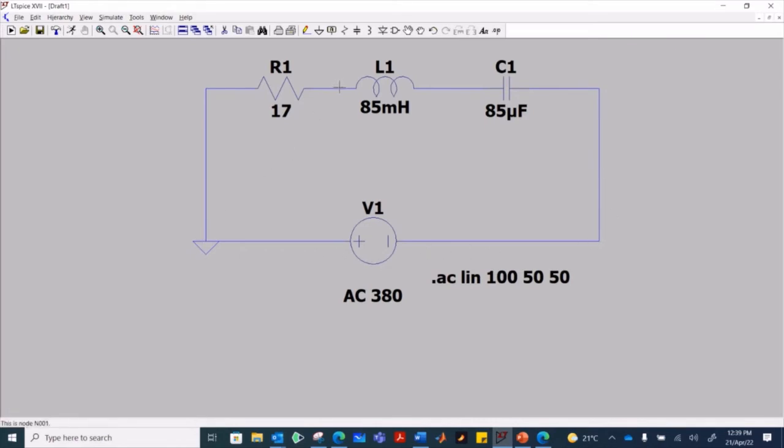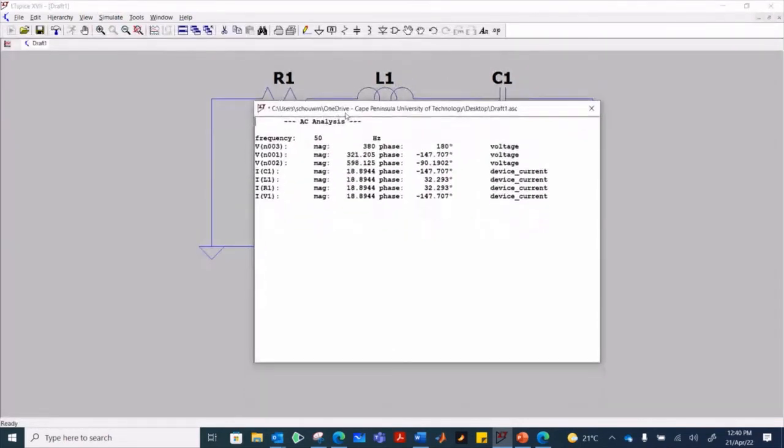So how we actually do this is that to find the voltage drop across a particular component, you're going to have to say node 1 minus ground. You're going to have to say node 2 minus node 1, and then node 3 minus node 2. So there's ground, node 1, node 2. Basically we have to take the voltages they give us and subtract them from each other. So I'll just resimulate this and get the values.